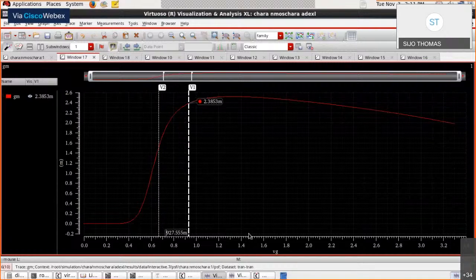I want to bring my MOSFET to weak inversion, that is, the linear portion of the gm curve. So we will reconsider the gm/ID value so that I can bring my MOSFET into weak or moderate inversion and carry forward the design.